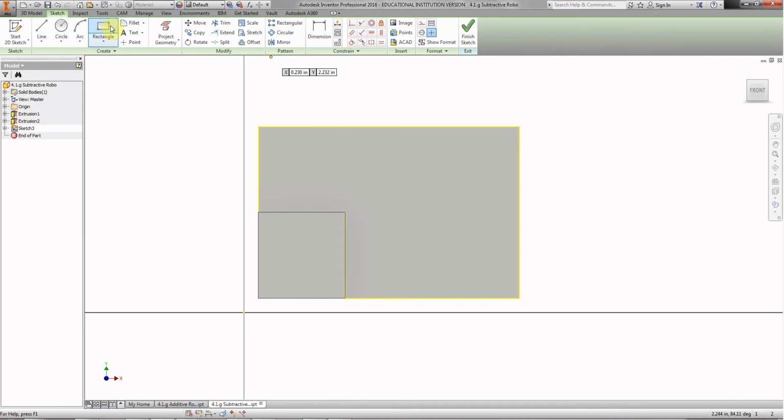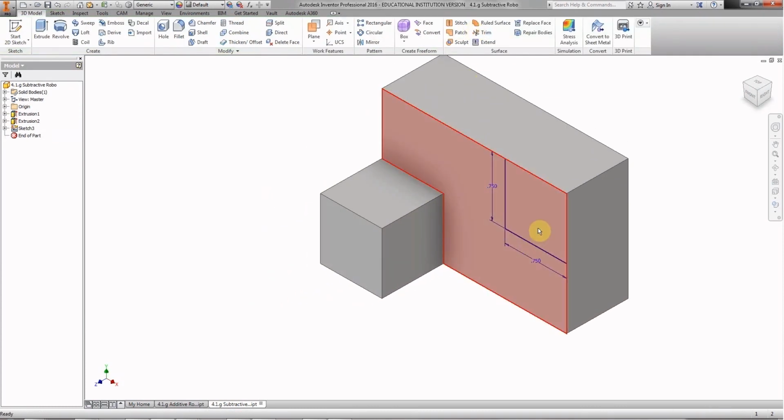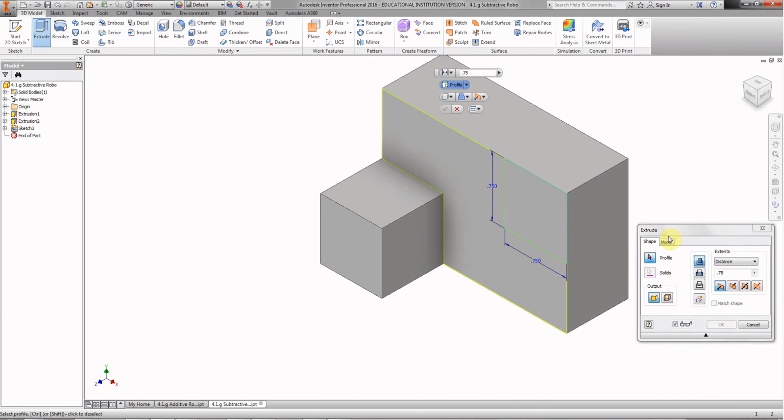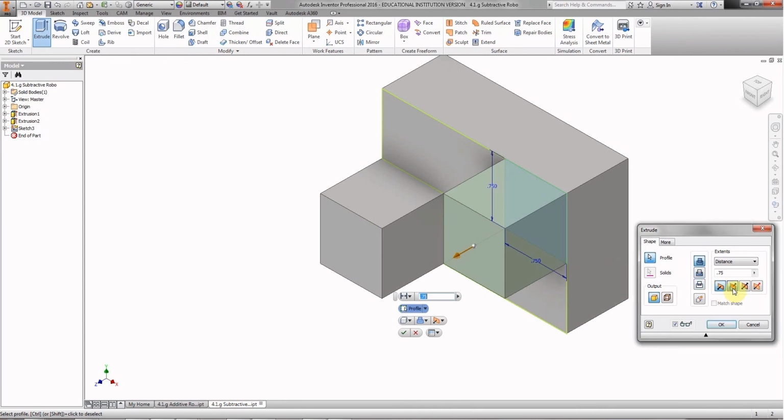I chose Rectangle. And we're going to choose the upper right-hand corner, get the green dot, click once, move downward, type in 0.75 for the width, 0.75 for the height. Looks good. We tabbed in between those two, and we'll hit enter. Right click, OK, finish sketch. Now we need to cut this piece away, so we choose extrude. Again, it's asking for us what profile. We choose this box right here, and instead of direction 1, direction 2.